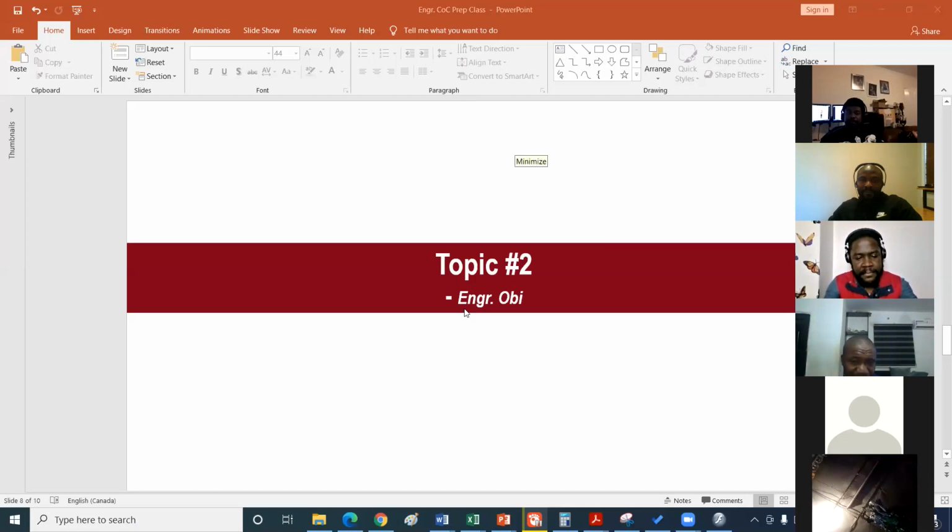What could prevent it is if the knob from manual to auto is not on auto. Also, if the generator is not running up to all three conditions that I have highlighted here, if any of them is not met, the generator will not come online.